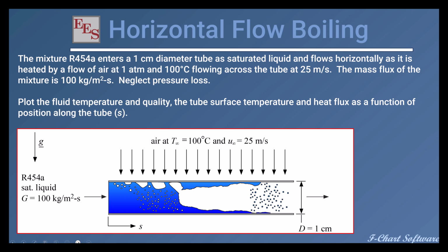But what we'd like to look at is what is the temperature of the fluid, so that temperature glide as it evaporates, and the quality, and then also the tube surface temperature and the heat flux as a function of position along the tube. And basically, how long does this tube need to be to almost completely boil the R454A? So, if I wanted to come out at 90% or 95% quality, how long do I need to have this tube? So that's the problem, and I'll give you some time to go work on it.